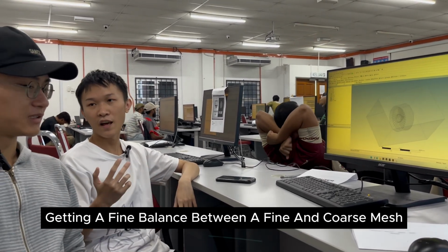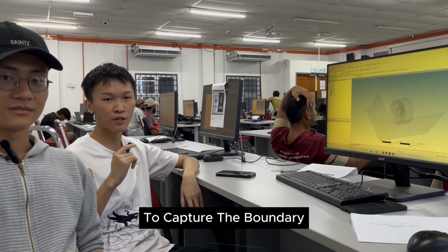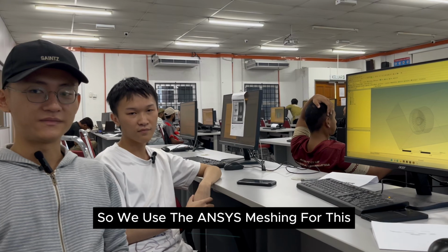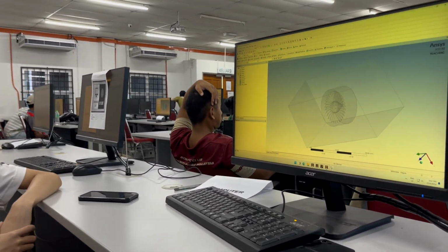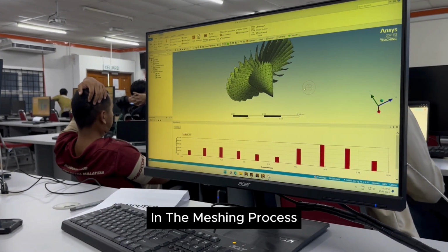Yes, getting a fine balance between a fine and coarse mesh was critical. A finer mesh around the blade surface was necessary to capture the boundary layer effects accurately. Exactly. So we use the ANSYS meshing for this. And this is an example that we did for the turbofan in the meshing process.